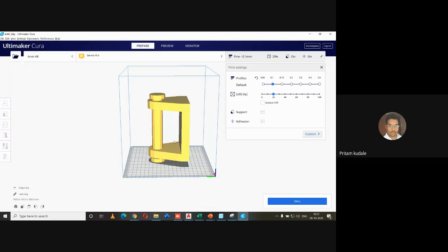So we will require relatively higher support material, because if we print this directly and release material here, and if there is no support, that material is going to fall down. So if you are going to print any overhanging part, you will require support. You also have to think that the orientation of the part is in such a way that overhanging material should be relatively less. So which parameter have we considered?